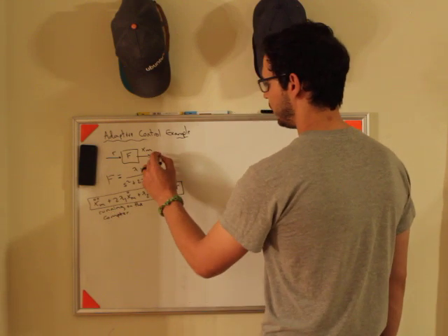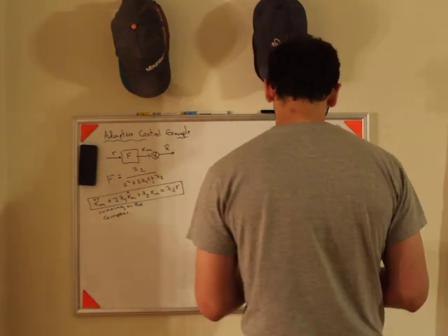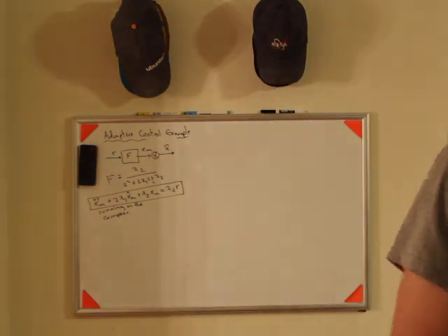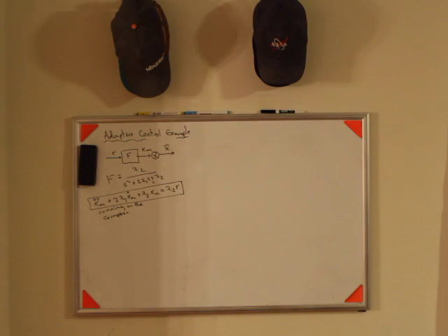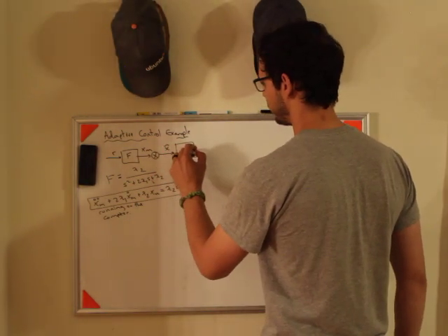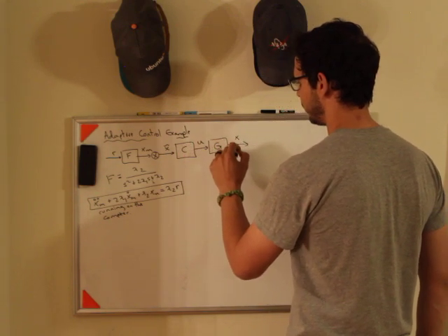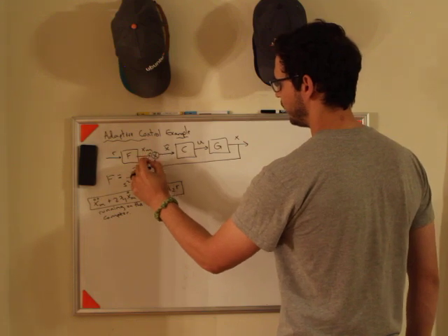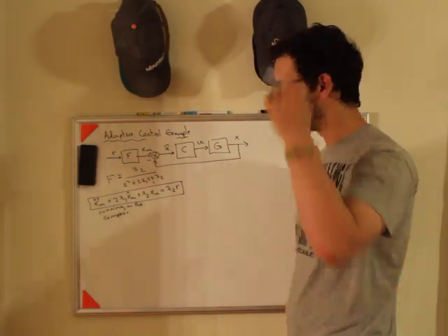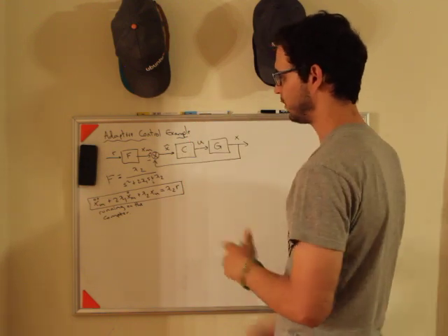Then this is going to have an error signal. I'm using the book Applied Nonlinear Control by Slotine. In the book they use x tilde here, so this is your error signal that's going to go to your controller, which is going to create your control input, which is going to go to your plant, and it's going to create your output. I'm assuming unity feedback here just to make the math a little bit simpler. The idea is how do you make C to stabilize the system?